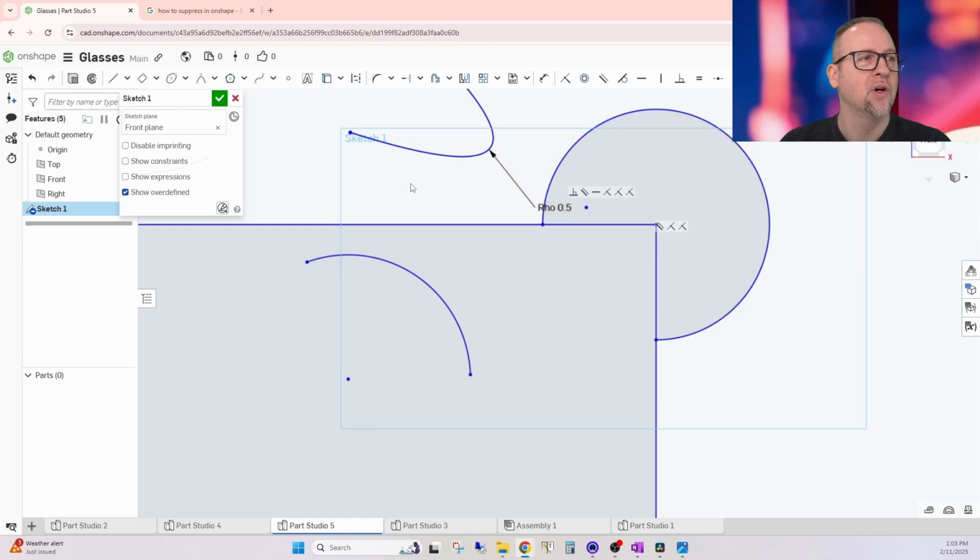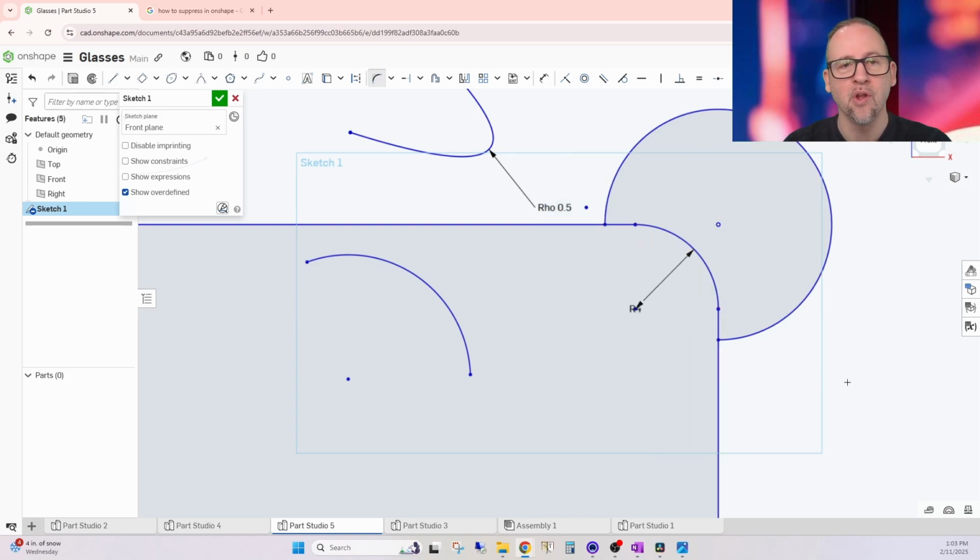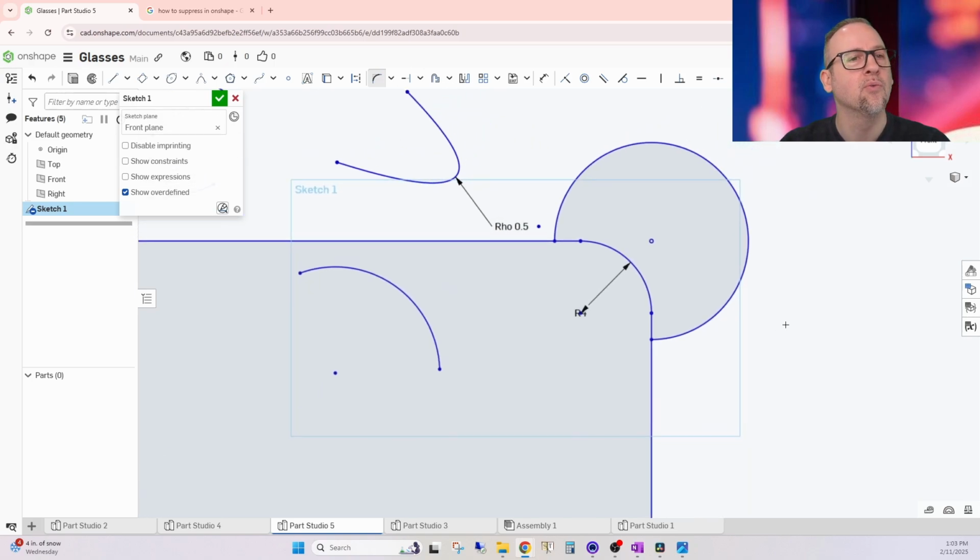And we'll go over to the inscribed polygon in a second. I want to go with sketch fillet first. This is the one I most commonly use. So you click your first edge, then the second edge, and then you pull, and it's got a left click there to get your number in. So let's put a 4 or something in there. And you can see that radius right there was just created.